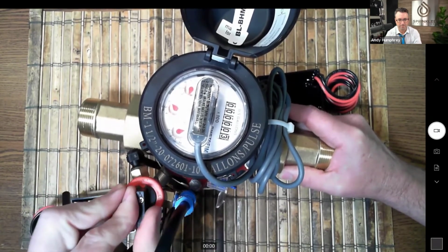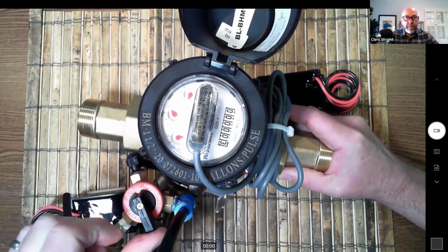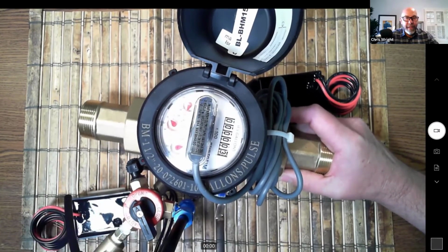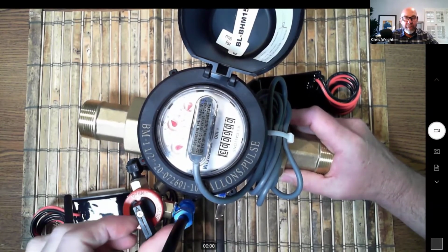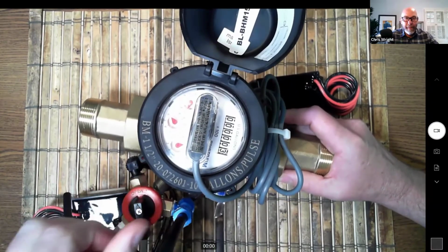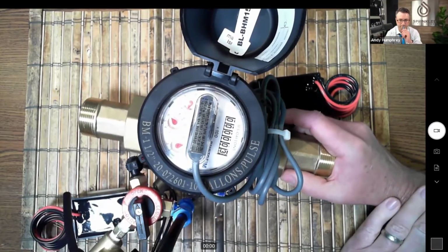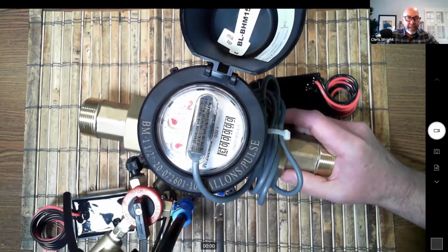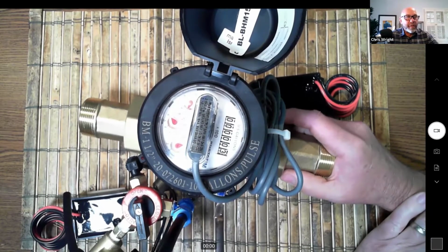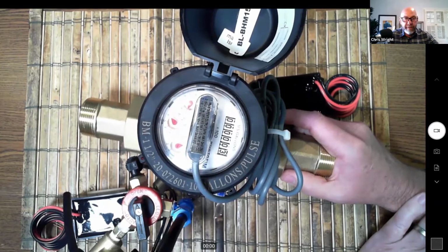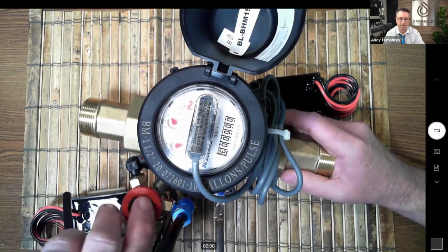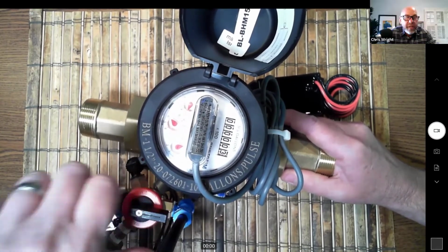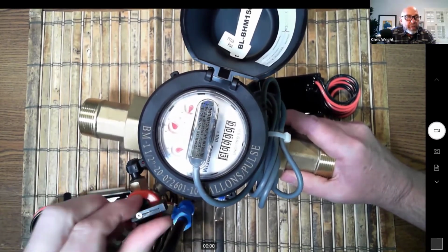So where do we want it if we're utilizing it? If it's in the open position, then what's it going to do? It's just going to run. It's open, flowing water, whether it's normally closed or normally open. If you put it to closed, then it'll obviously close, which means it won't allow the diaphragm to open. And if it's in auto, then it's being automated by the system, managing and monitoring the flow based on the design flows and operation programmed in the controller.